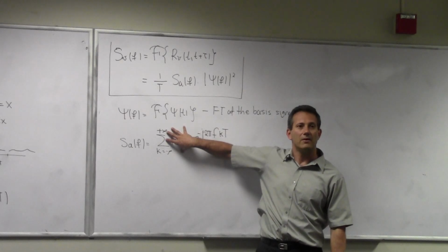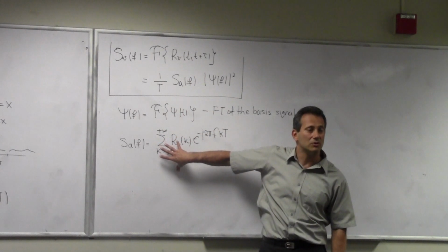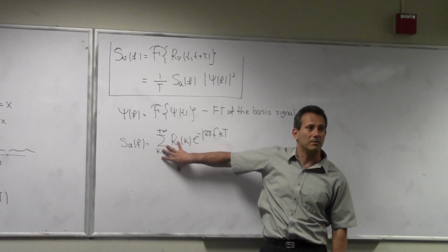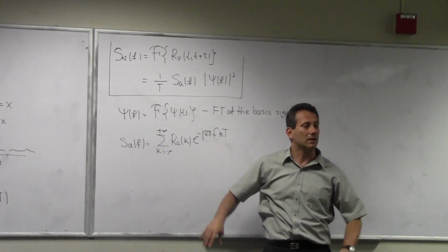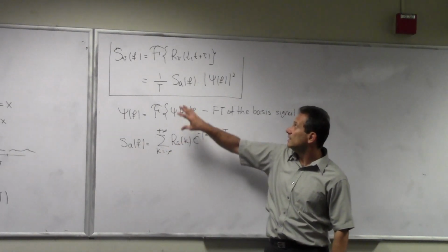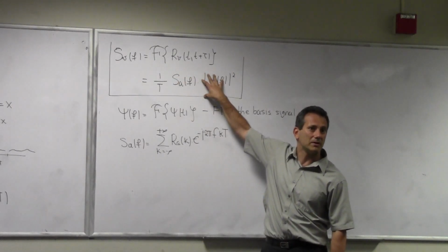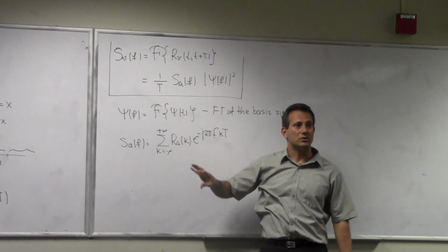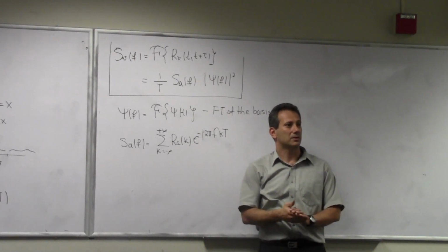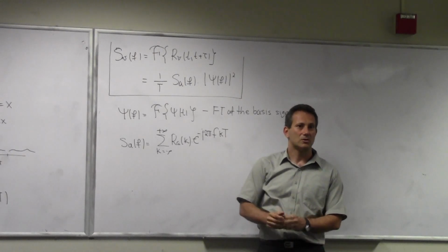And what we learn here is a beautiful result: if you do your statistical encoding properly, meaning that you decorrelate your symbols and make them equiprobable and uncorrelated from one another, then the footprint of your signal in the frequency domain depends only on your pulse selection. So all I have to do is focus on selecting my pulse so that I minimize my intersymbol interference. That's the result here.